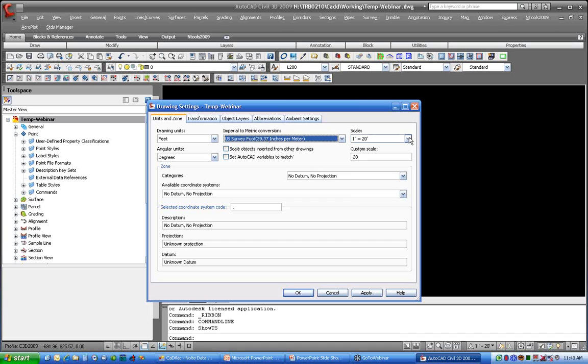for this drawing. The Scale tab is where we can set our initial model space annotation scale. So if I pick 20 or 30 here, that's going to be equivalent as setting it down here on the command line. All right. I'm going to leave this one at 20.